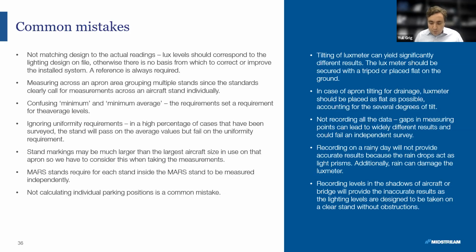Of course, some airports need to be assisted by third parties, by independent surveyors. But even in those cases, even if it's a third-party company, make sure someone is accountable and responsible, checking those values, because ultimately you are responsible for ensuring that it is in compliance with regulations. Also, lux levels should be carried out after every new lighting installation. If you've been doing your light level checks and they're fine, and you've installed some new luminaires, or put a new mast in place, that area should be checked and verified and added, and after that, on an annual basis, it's inspected.